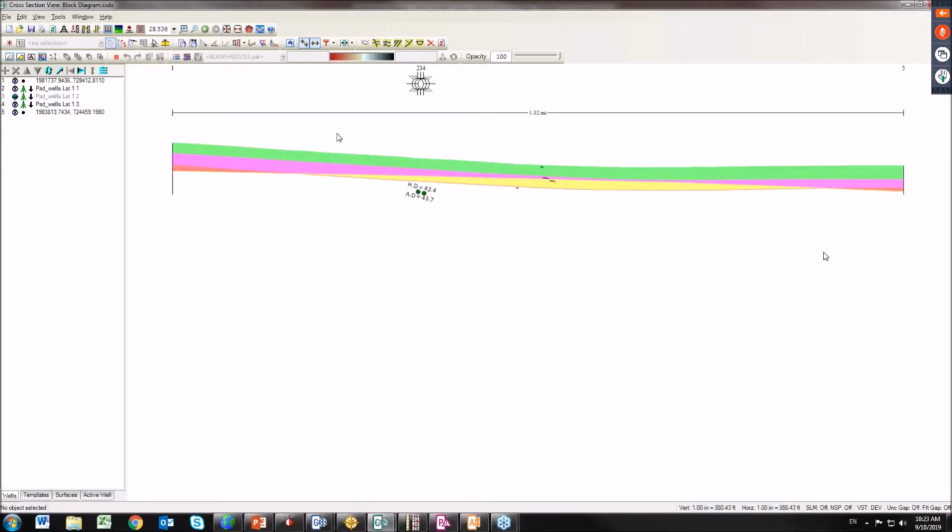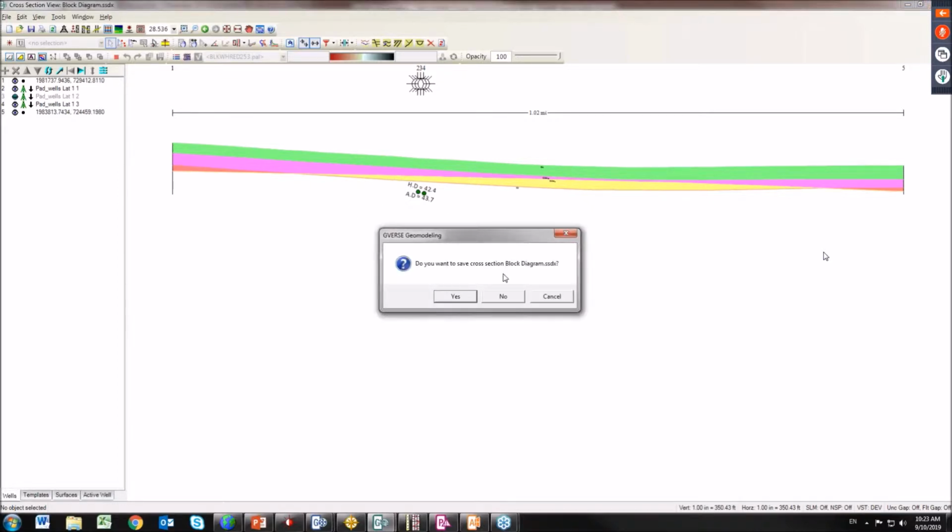It's going to show you, if you have a lot of wells, directional wells, and you're planning a well, or you want to see what's going on in that area, you can display those wells like these little dots that are directional wells, and imagine those dots are coming out of the screen. So you can see the distance between each one, the horizontal distance, turning off the information, and have an idea, if you want to plan the wells, or if you're doing a geological interpretation, which one is the target of those wells.